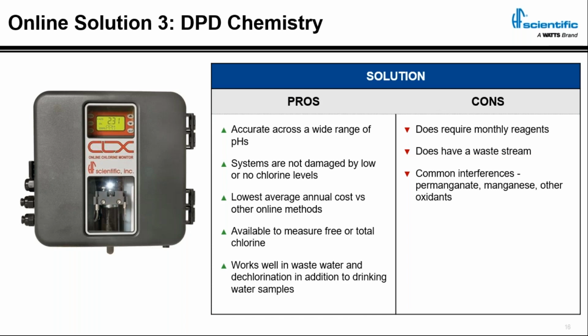And it's important to note that some manufacturers say, well, you can change the measurement time on ours, because a typical measurement time is about 3 minutes on a chlorine analyzer. For instance, ours goes up to 10 minutes, but that doesn't really save you any reagent cost, because the reagents are really only good for 35 to 40 days after you've put them in the analyzer. They'll start to oxidize in the bottle and cause error. So to me, running a continuous analyzer at a batch of every 3 minutes makes more sense than throwing out reagent at the end of the month.